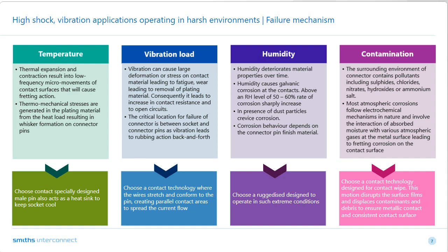Humidity is a big piece in this discussion, and goes with it is contamination, because often HVAC systems are put in place where the natural environment is dusty. So it goes without saying the contamination has got a piece in this failure mode analysis.